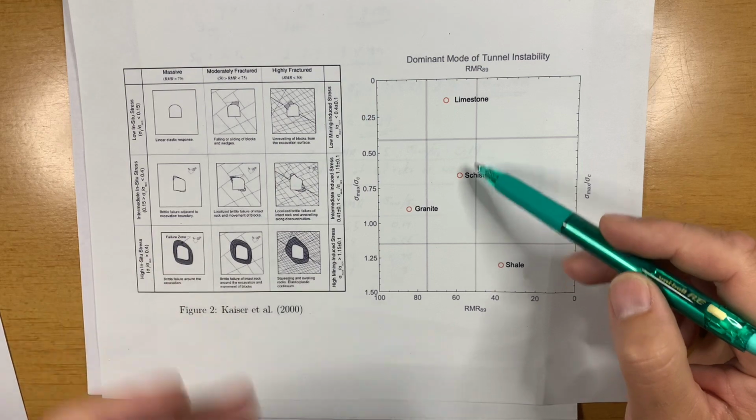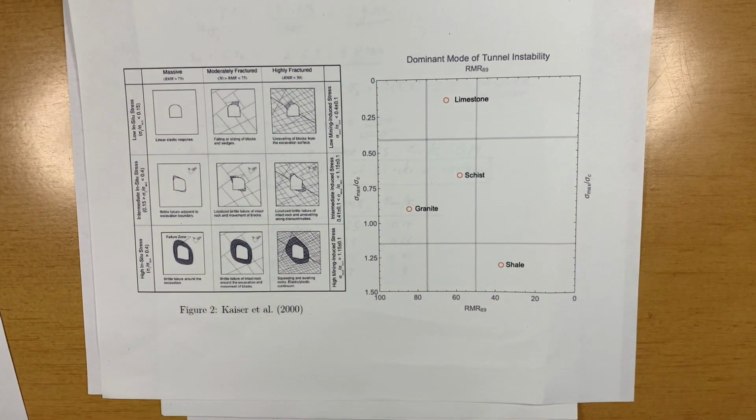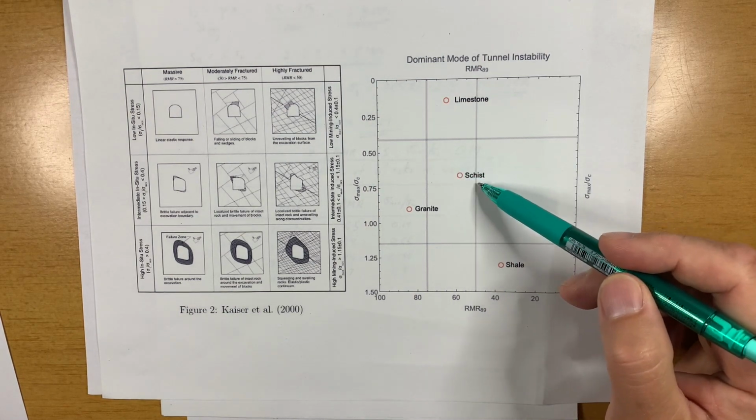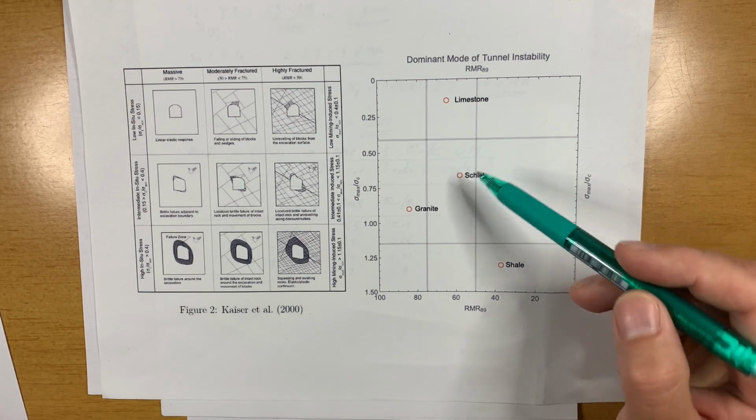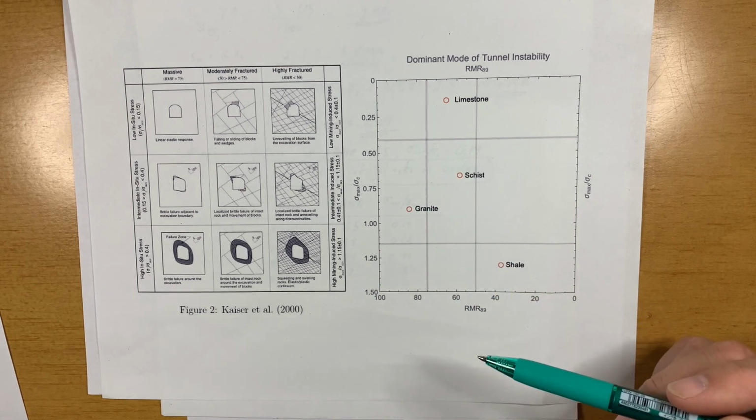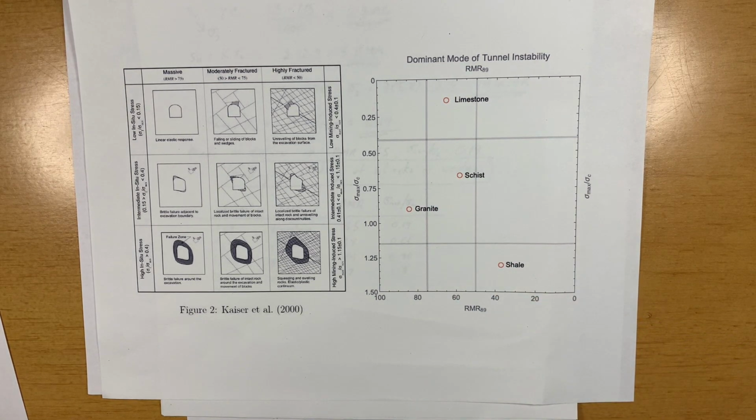Schist is going to be fairly similar to the limestone, but there might be some brittle failure and so on that might affect the type of rock bolts, or the shotcrete might become more important than it was in the limestone, where it wouldn't probably be as effective. And then we go into the granite. In some cases we might expect some brittle failure, but overall a fairly good quality rock in not overly high stresses. So that might require some kind of energy absorptive ground support,